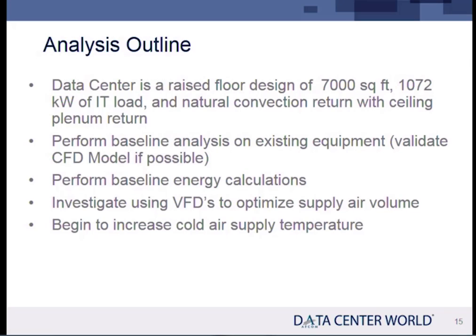So we're going to have a 1 megawatt data center here. It's going to be natural convection with ceiling plenum return. We're going to do a baseline run on it. Always validate your models if you can. This is great to do on existing data centers: go in and take a few samples to make sure that the model you built actually represents the real world. But in many cases, you haven't built it yet, so it's the best tool you have.